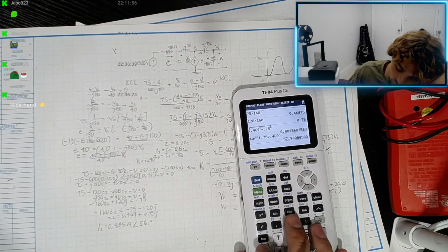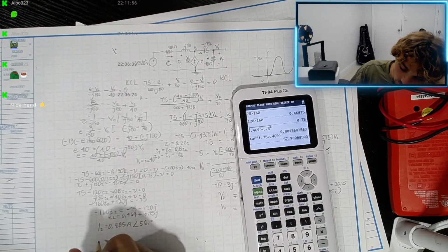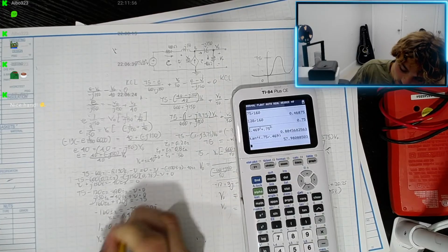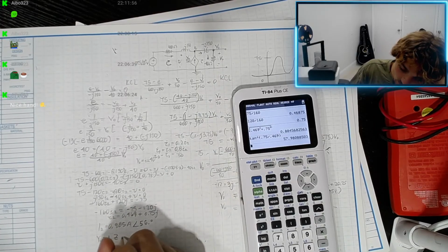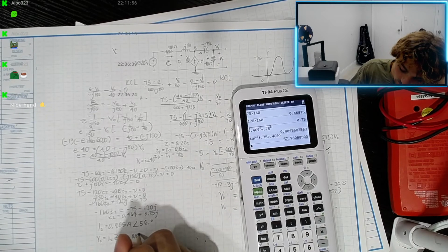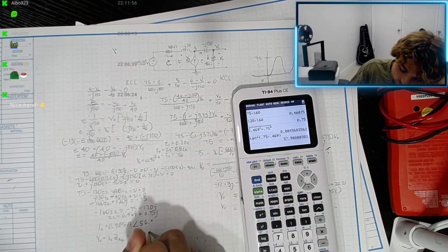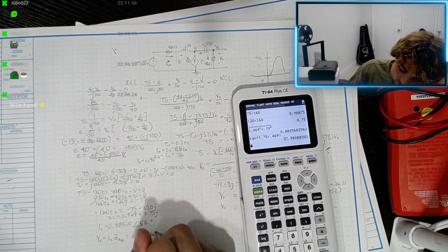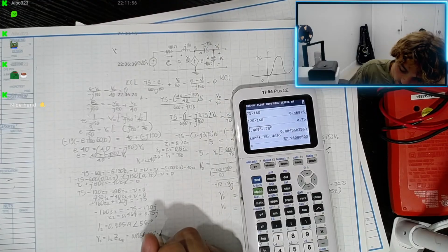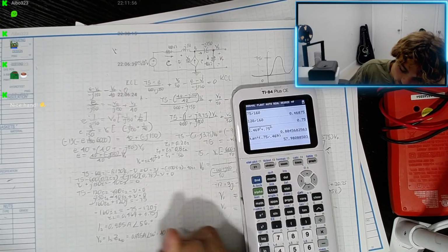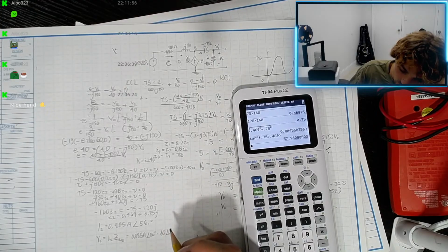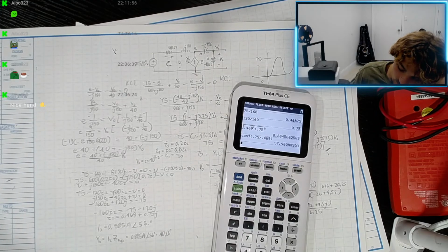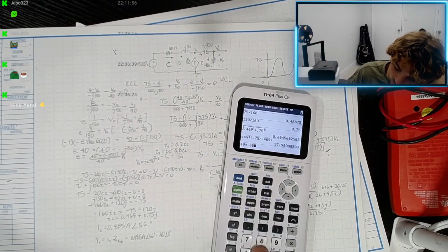Alright, I2. Now VL equals I2 multiplied by the 40 ohm resistor, which equals 0.885 amps at 56 degrees multiplied by 40 at 0 degrees. So 40 multiplied by 0.885.